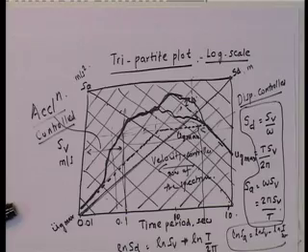In the short period structures, inertia driven, acceleration determines the peak. So, SA determines what you get. Okay. Then you have the very long period structures, where SA does not give me anything, it is displacement controlled, the peak ground displacement gives me, and therefore, it is really the deformation that determines what kind of forces the structure is subjected to.